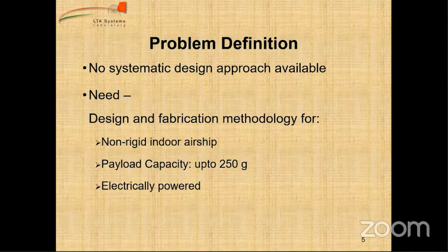Yeah, but for an indoor airship, a turboprop engine is not a decent one. We cannot use a turboprop. And as you know, an airship is a slowly flying vehicle, and in the case of an indoor airship, there will be limited space available to fly. Sir, for indoor, we can use an electric motor. Yeah, I am recommending that please use electrically powered engines or motors. So why am I recommending this? Can you guess? Lesser in weight.